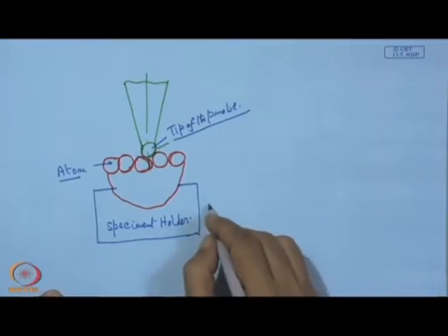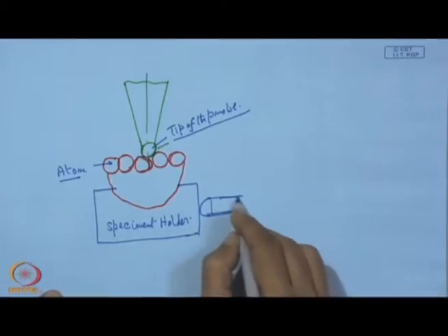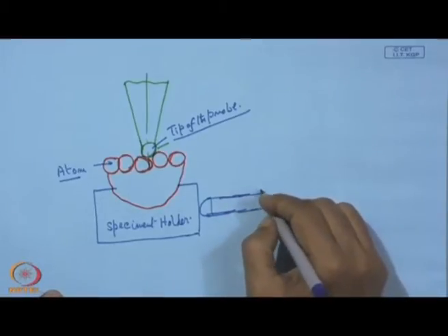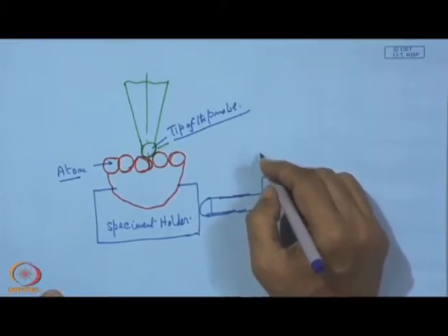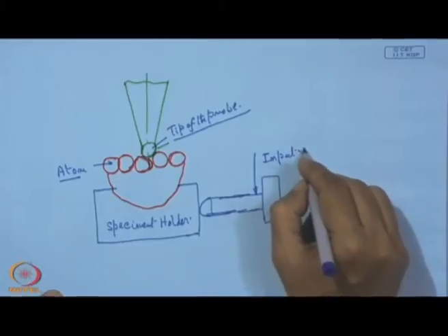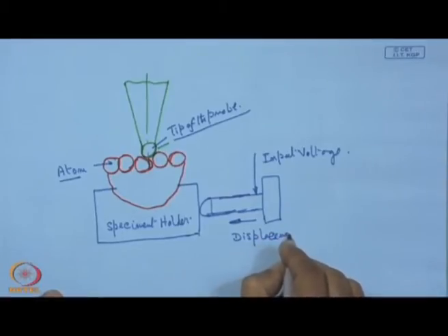That will be driven by one actuator, and this is actually a piezoelectric actuator. Now, in this piezoelectric actuator, if we apply a voltage in this direction, that is the input voltage, then we expect a mechanical displacement, a microscopic, very small amount of displacement.